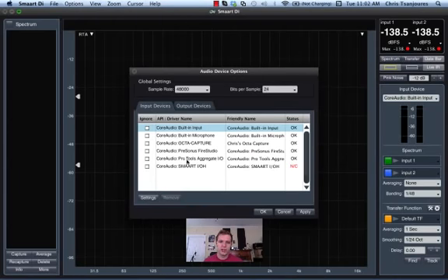So here we have the driver names, and you can see the driver shows up as Core Audio OctaCapture, and I've renamed it Chris's OctaCapture. Because I'll only be using the Smaart I/O and the OctaCapture, I'm just going to go ahead and hide the other interfaces that my computer sees. So when I relaunch DI, if I have my Smaart I/O connected, which I'll show you in a later video, that will be the default device, and if not, it'll always go to the OctaCapture.